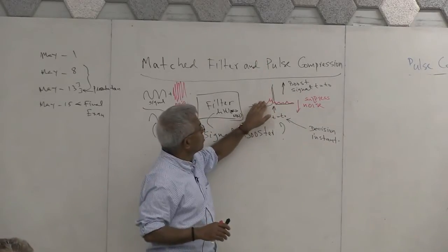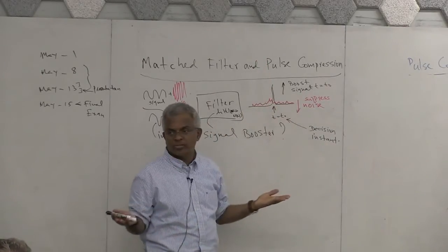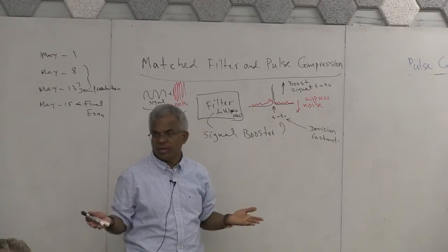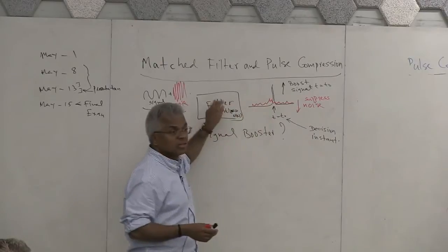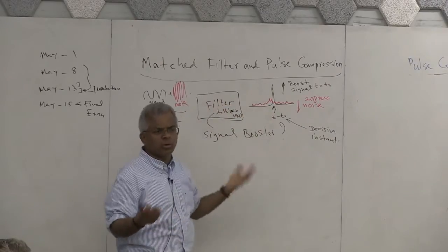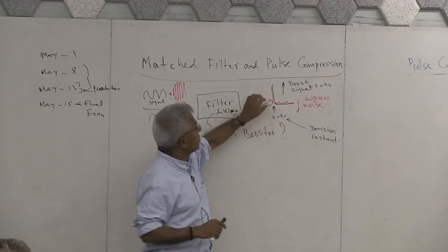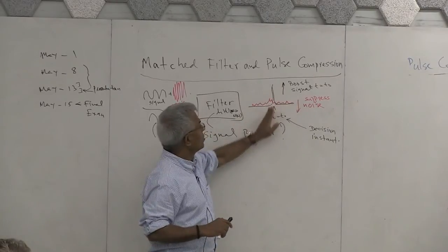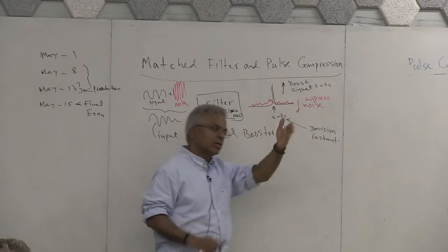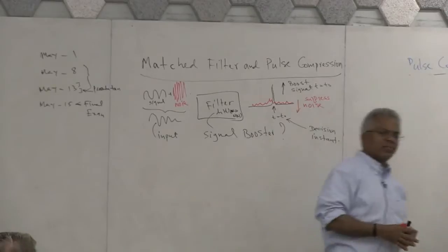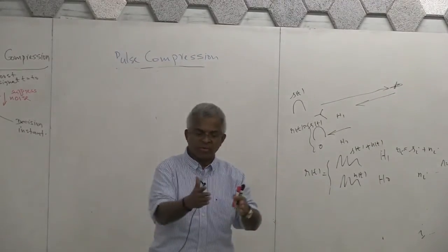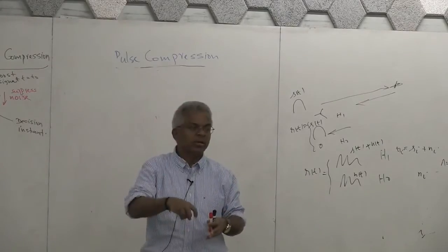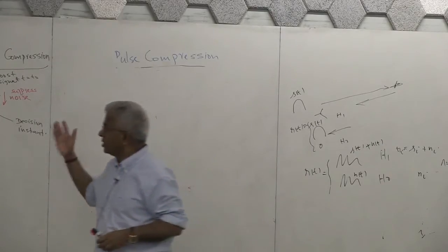We can say, why not boost here also at the other places? What is the point? Because remember, nothing is free. If you keep boosting the signal here, this has to work harder, or it may be a more complicated filter. And anyway, that information is useless because you're only going to make the decision here. In communication, this is very relevant because each bit is going to come at T0. So after the bit has come in, you make a decision at that time. Then you repeat it.